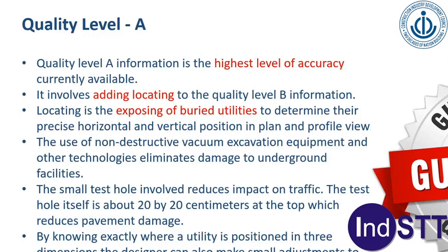And depending on the project, we decide how these maps should be printed. But the fact is that any map becomes a subsurface utility map prepared using the process of subsurface utility engineering only and only if every utility has an associated quality level. If utilities do not have an associated quality level, it is not an acceptable SUE map.